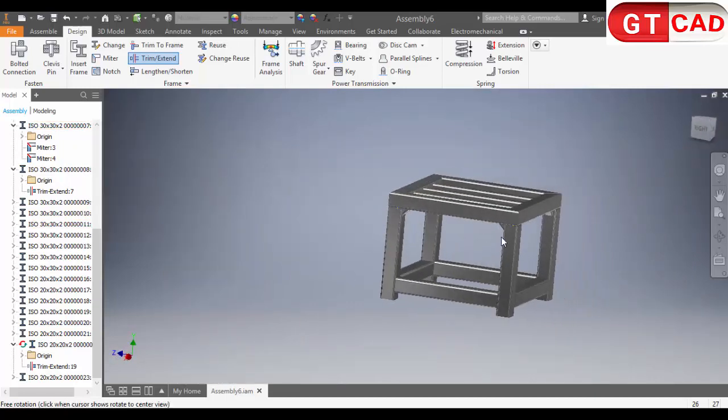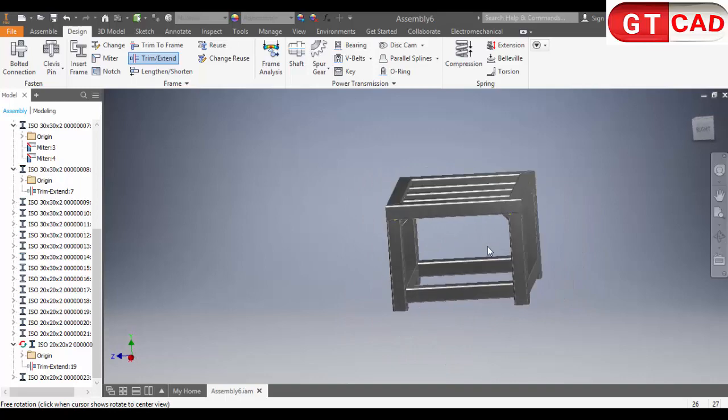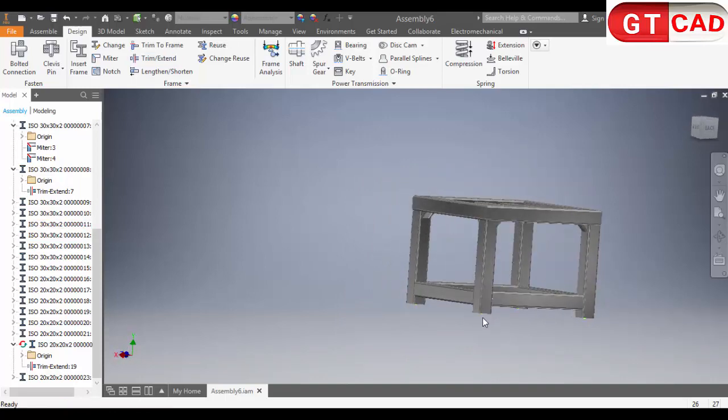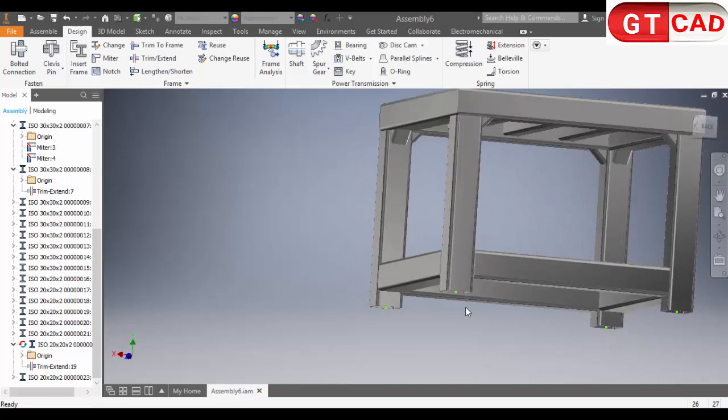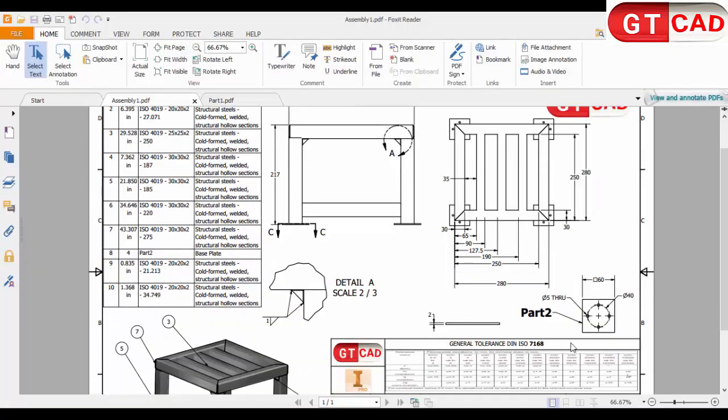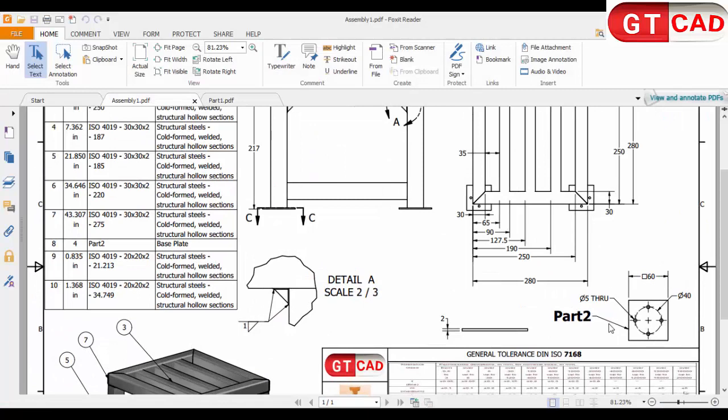Okay. Our structure trimming is finished, just the base plates remain. We have four. It's in the drawing. We have the square plate. It's steel 37. The thickness is 2 millimeters and the dimension is 60. And we have 4 holes that are placed on a pitch circle.